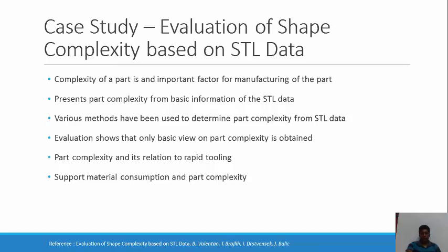The complexity of the shape of a part is an important factor for all manufacturing procedures. Whenever conventional machining is used, part complexity presents a key factor in determining the optimal way of manufacturing. Also, whenever rapid tooling is used, for example silicone rubber molding, the complexity of the part determines the parting plane layout and eventual tool construction such as inserts, cores, etc.